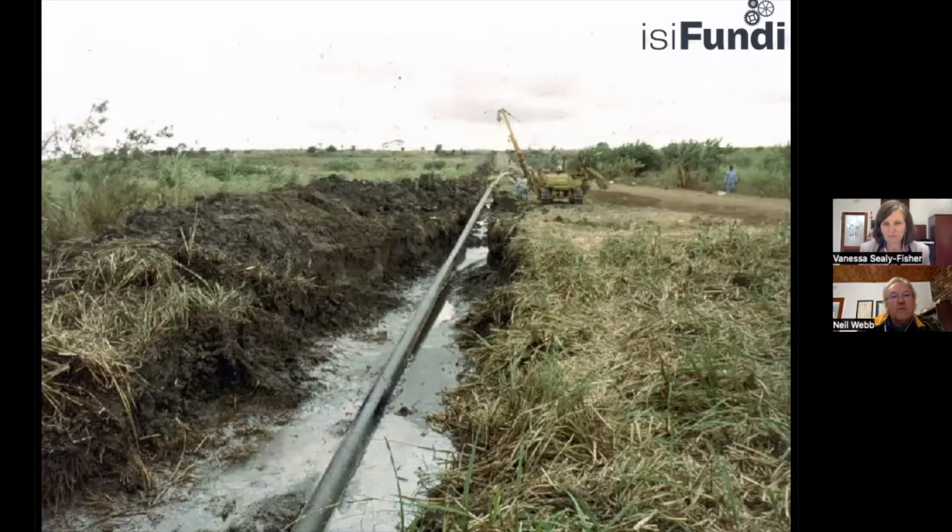And so in this project, we then did a current demand survey. We had the resistivity data. We had pipeline potential data, because there were test posts every 2 kilometers. We knew which cathodic protection systems had been working and which had not been working. And we obviously had the topography as well. And we knew where the leaks were. So we had a huge amount of information that is all part of the pre-assessment phase.